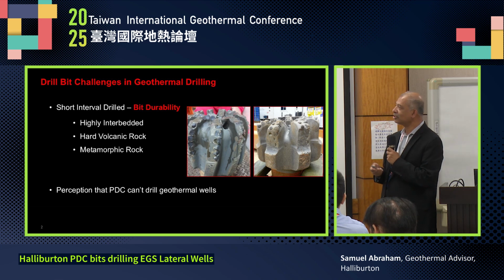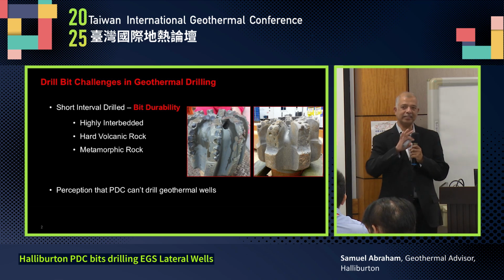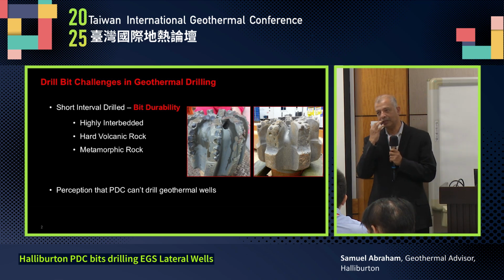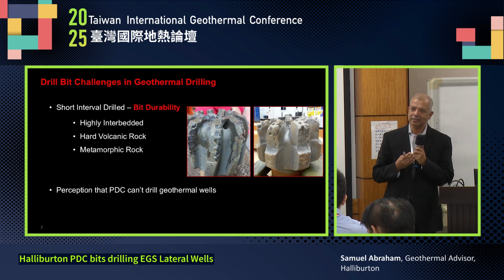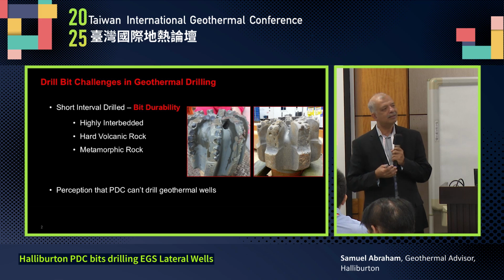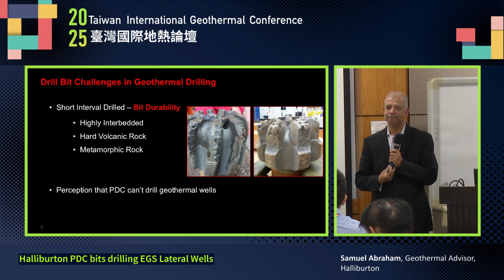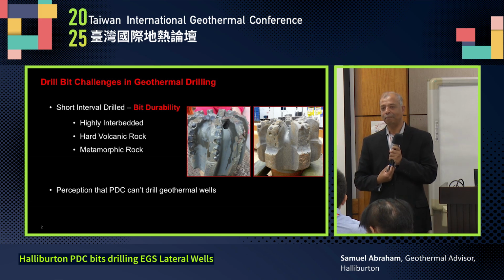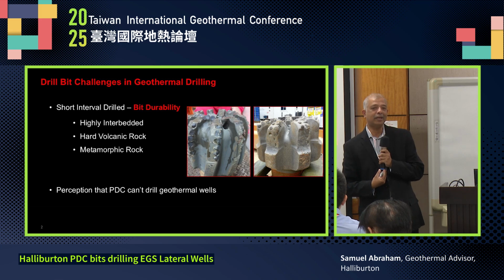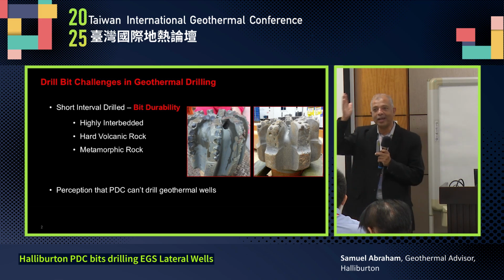When I refer to Taiwan as a whole, or this region, you're looking at highly interbedded formations, number one, then hard volcanic rock. Some of the minerals in those rocks, I can almost bet you, we've seen chip away a PDC bit, and give it about 2 or 3 hours, the PDC bit comes out with probably no hair on the head.